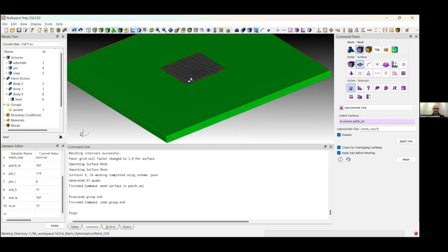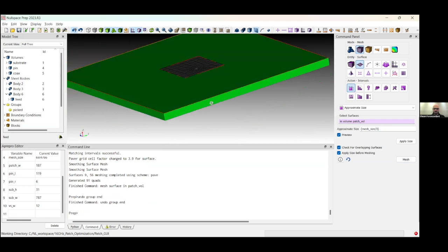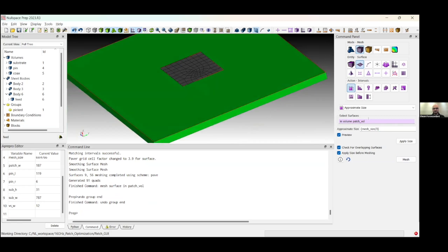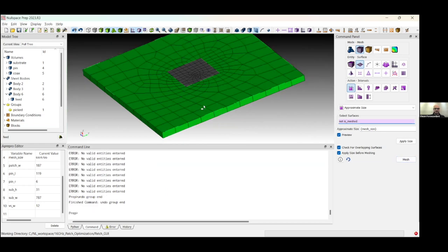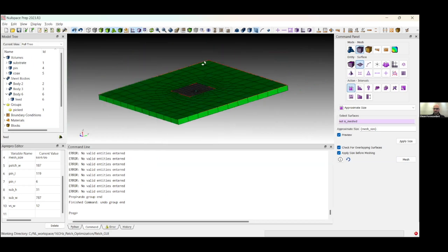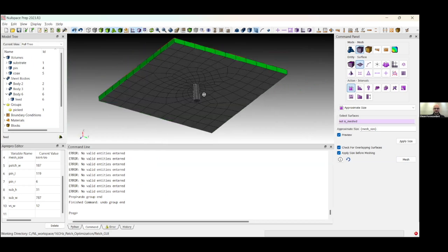So right now we have done all the parts that need fine tuning for the mesh, and then we can go ahead and mesh the rest of the parts that are left, based only on the baseline of the mesh size. So we can go ahead and write select surfaces not is_meshed, and I will select the surfaces that are not meshed, and then I press apply. Then you will be able to mesh the rest of the parts. Yes, so now we are done with the meshing part.